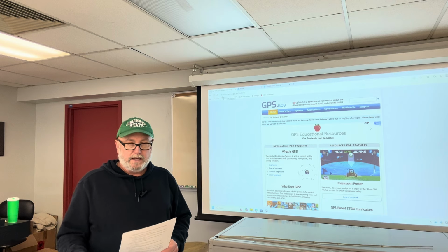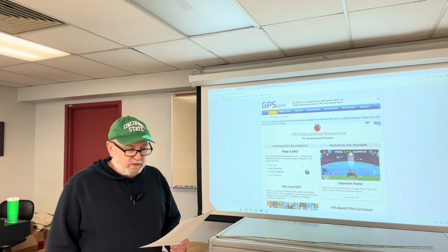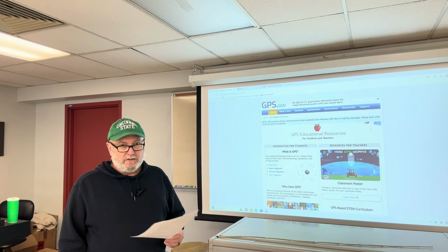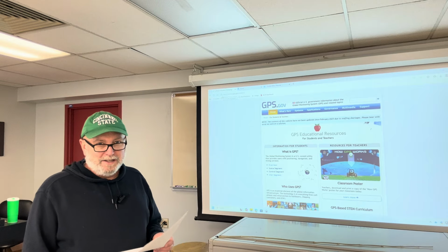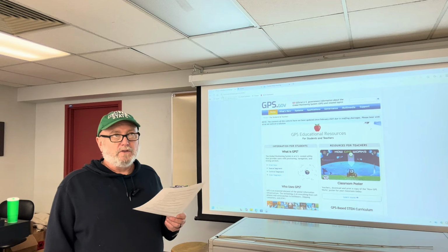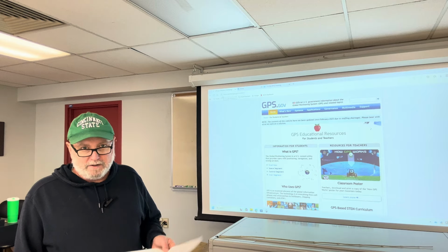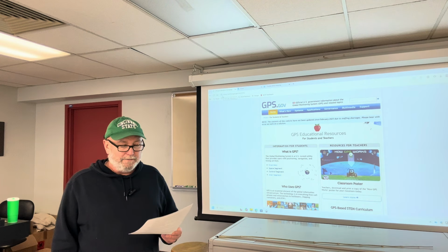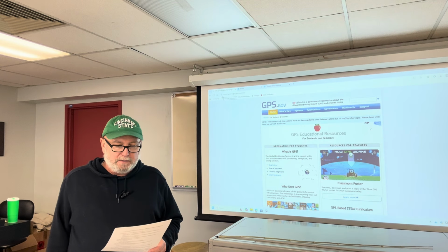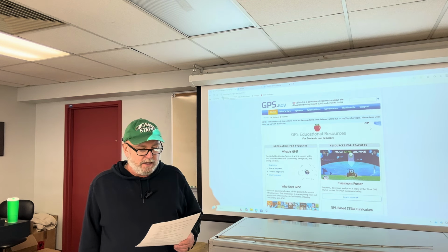Some quality control and validation concepts. Use redundancy, extra baselines or loops, closure checks, and least squares adjustments. I say this in a lot of other classes. I say it a lot, beating a dead horse here. One of my favorite sayings for surveyors is that redundancy builds confidence. Check, check, recheck, and then check again. Compare to achieved accuracies with specified FGCS order, document internal and external accuracy.